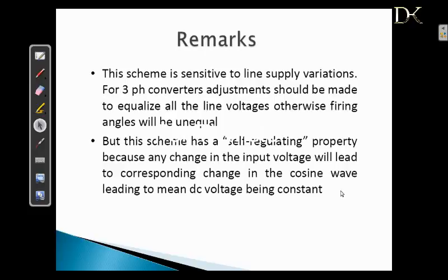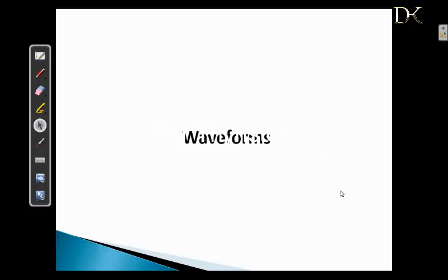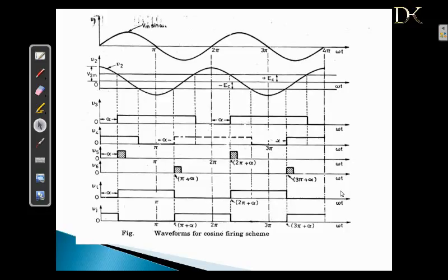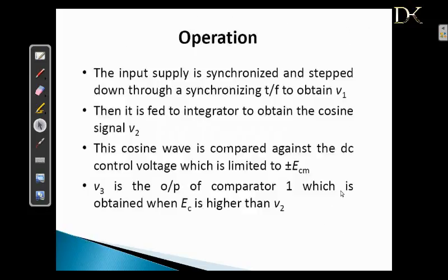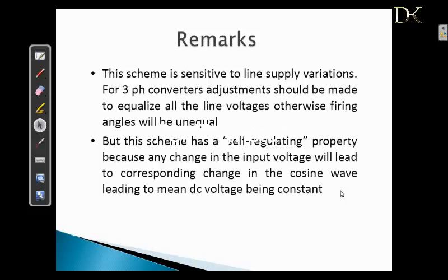See, the size of the control scheme circuit increases if you increase the number of phases or the number of pulses, because the firing pulse is produced individually for each thyristor. You can overcome this by using cosine time multiplexing instead of individual timing control. The cosine control scheme also applies to the dual and cyclo converter.